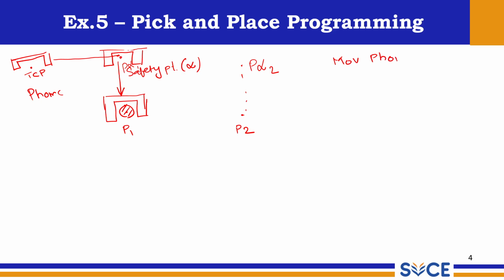So how do we do the program? Move P home. Now we don't know what the gripper condition is, whether the gripper is in open condition or in released condition, so we are always supposed to give that particular command first: M_Out(15) = 0. If the gripper is in closed condition, it will open. Students, I often emphasize this is 0 and not the letter O. It is not caps, it is regular, but M is caps. So please be very cautious.